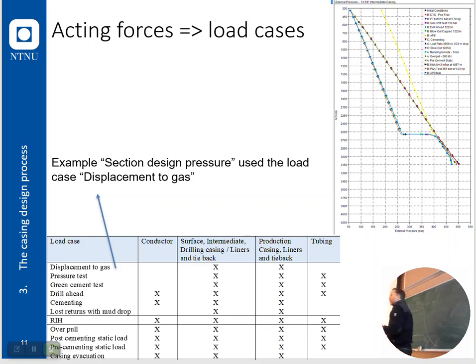As we talked about for the open hole design, the kick tolerance. We don't do kick tolerance unless we have a BOP, right? Because we are not closing in the well. And here's the same thing too, displacement to gas. You can't really displace the well to gas unless you have a BOP, right? So that is a logic part too.